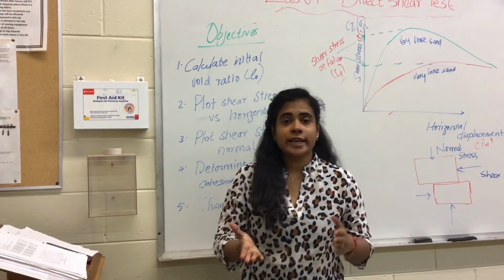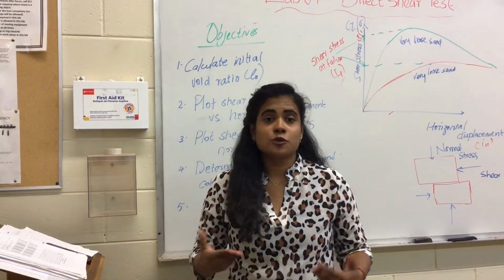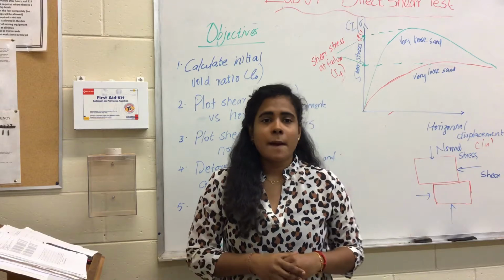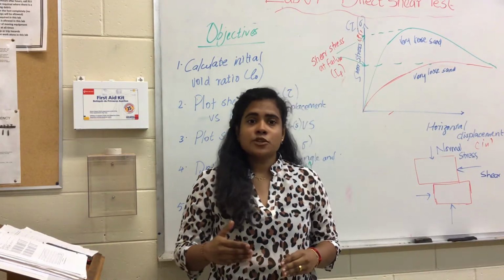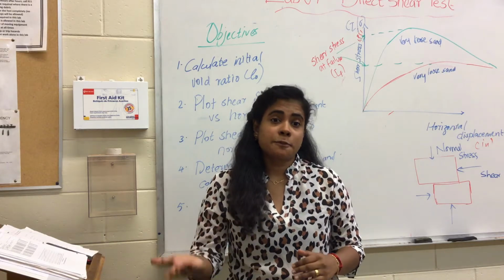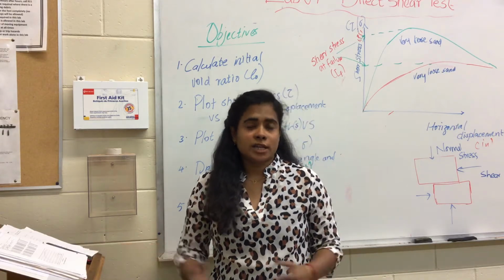Direct shear is a quick and inexpensive method used to find out the shear strength of the soil. But one of the disadvantages of direct shear is that it tends to fail the soil in a designated plane, which will not be the weakest one.